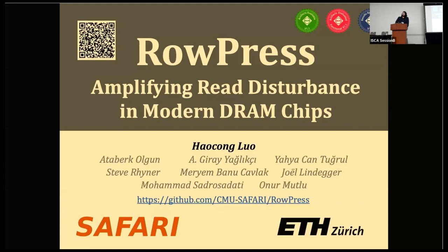Yes, so the operation that matters is the activation of the row. Yeah, I agree that, let's say from a systems perspective, both read and write can trigger activation. So write can also work, but yeah, we use the term read disturbance because it's kind of a legacy term from RowHammer times that we carried over.